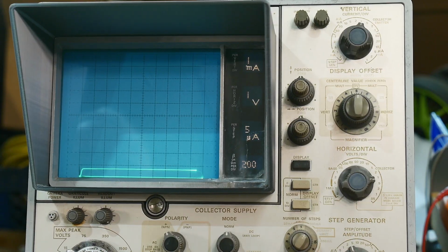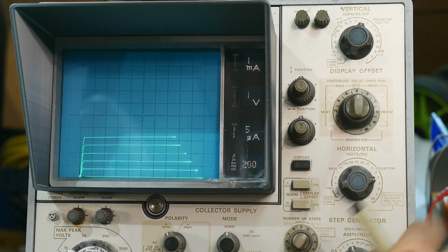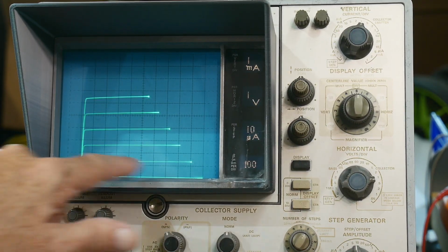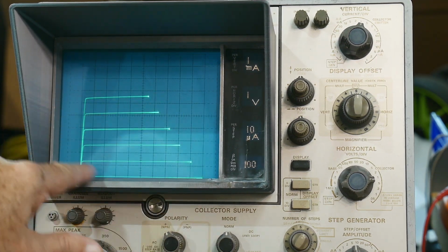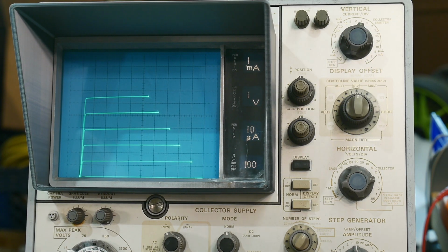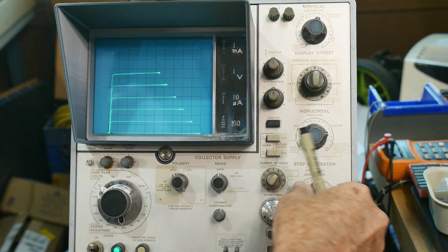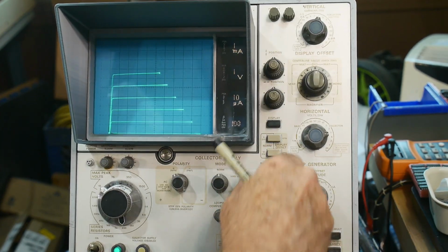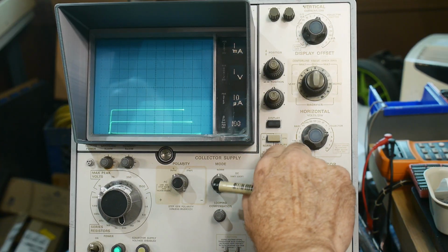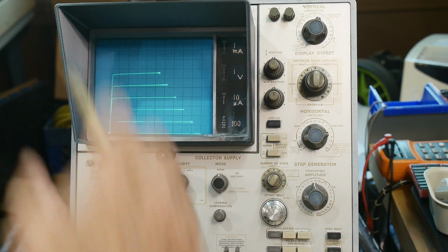Well, what if we want to look at this all at the same time? Well, we can say, well, just do that for me automatically. Just go ahead and multiply. Just keep doing those, right? So it's going to have 10 microamps, then 20 microamps, then 30 microamps, then 40 microamps, then 50 microamps, okay? It's just repeating those things for us. It's called a step generator. And so this dial over here tells us how big of a steps do we take. Do we take small steps or do we take big steps? And then this tells us how many steps. You want 2 steps, 3 steps, 4 steps, 5 steps, 6 steps, go all the way up to 10 steps, okay? Different steps.